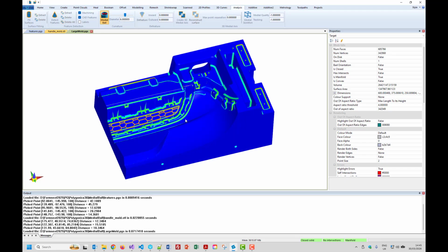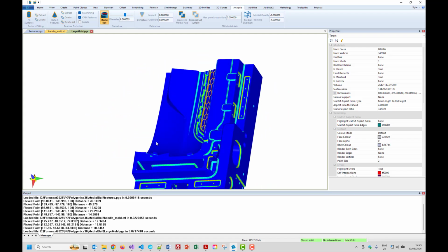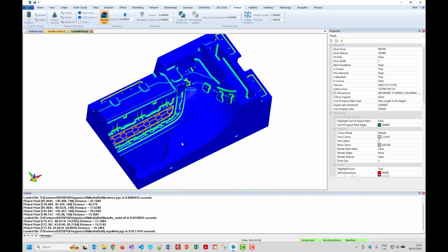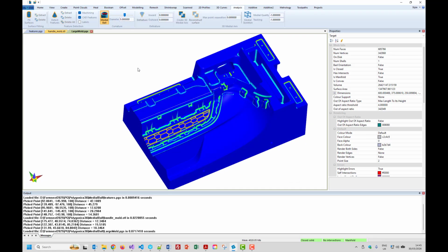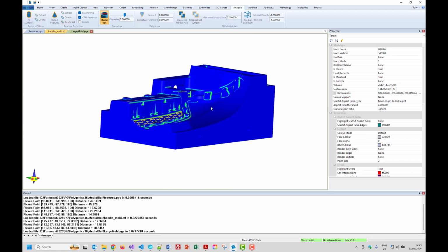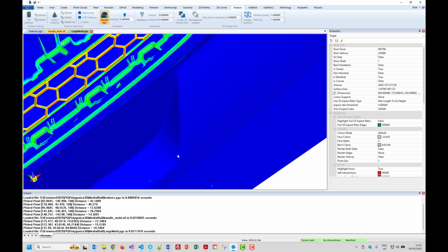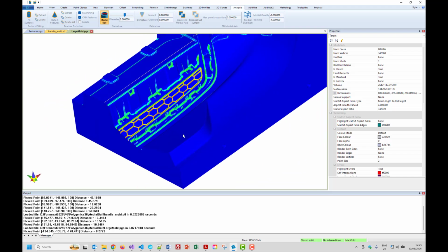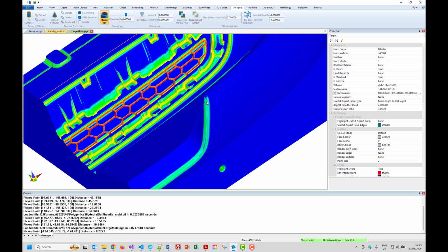But the medial ball is going to tell you very quickly, and as you can see, it's done all over the part. There's a lot of information here. So it's picked, let's say 6, let's just make that 5 for the sake of argument. Say we've got a 5mm cutter here, and understandably there's no problems machining these freeform surfaces here, and you can get into there with a 5mm cutter even. If I double click on it, it's telling me 8 mils. So let's say we had a 10mm cutter, and then you can see we can't get into that bit. We need, with 10 mils.